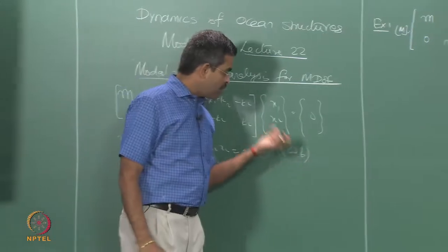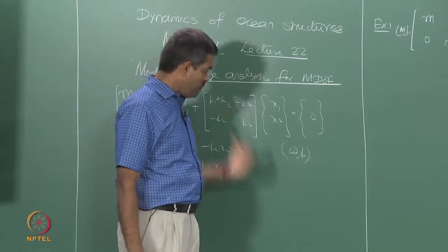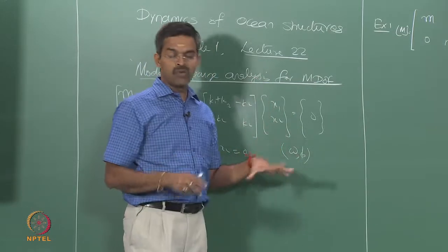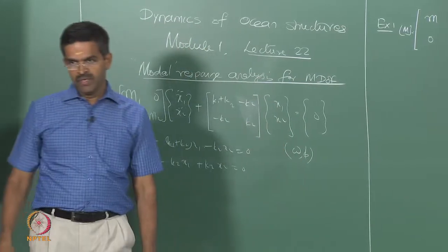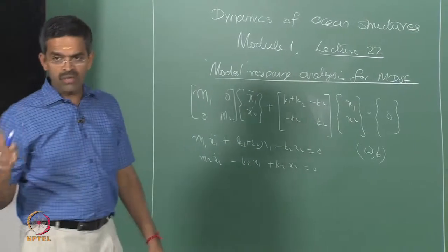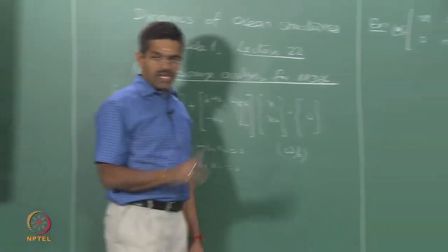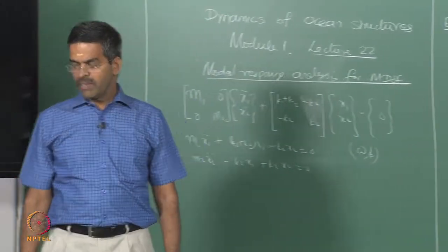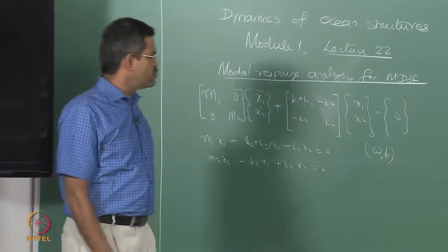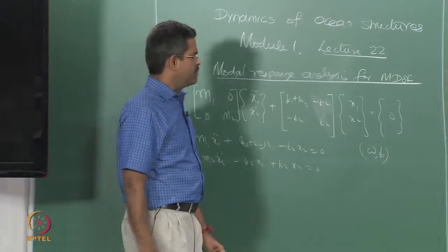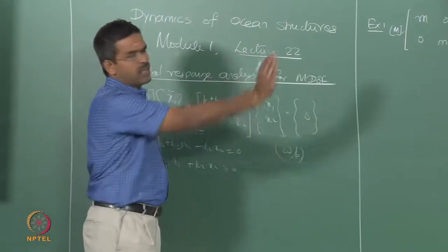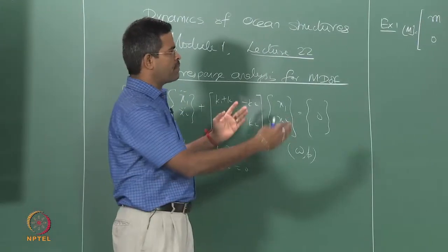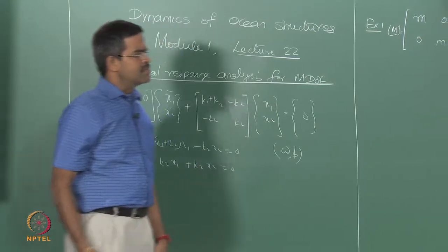They will be and they must be and they should be present in a system even if the system is not excited. So, it is a characteristic which is a natural property of the system. So, omega and phi estimates should not vary and depend on f of t at all. It is a free vibration characteristic essentially; it should not depend on the forcing function at all. So, f of t does not bother here at all in my equation, and of course, I do not want to include damping here because we will talk about damping estimates slightly later in the successive lecture.